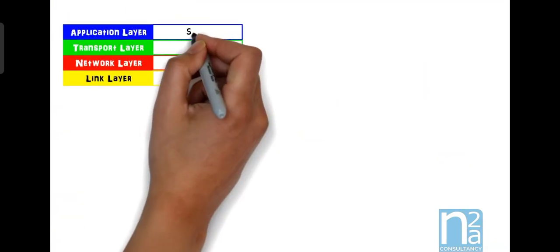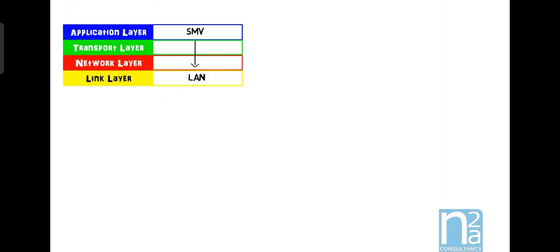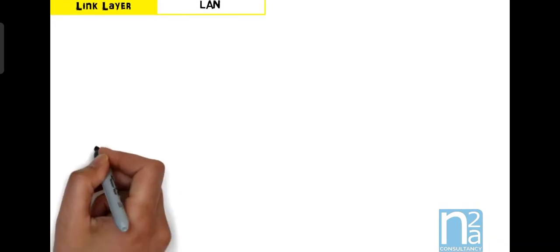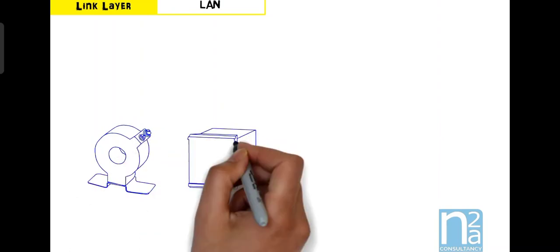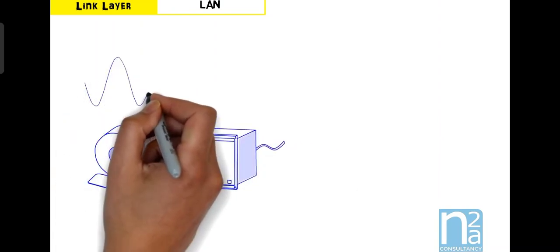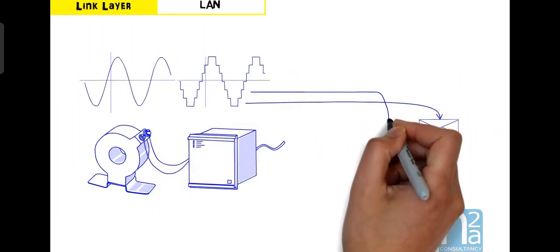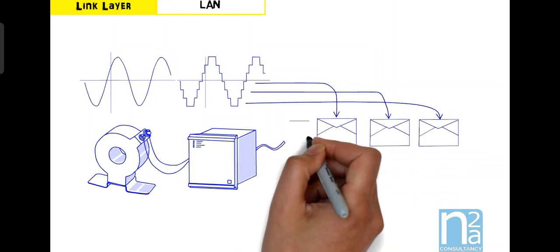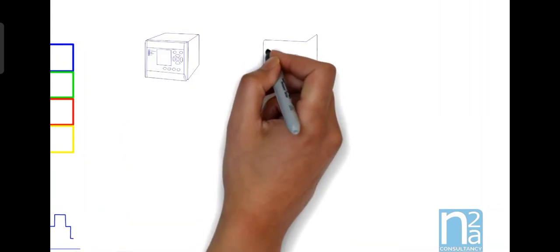The last communication protocol is SMV, which stands for sampled measurement value. As with GOOSE messages, SMV application is directly linked to the link layer and uses a publisher-subscriber mechanism. SMV will allow current and voltage to be sent in a digital way, across the process bus, by a digital instrument or via a merging unit. A merging unit transposes an analog signal into a digital one, a discrete value tagged with synchronized time. This voltage and current measurement could be used by any IEDs which need the information.